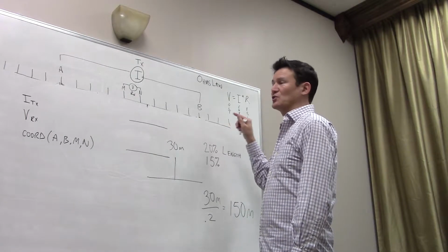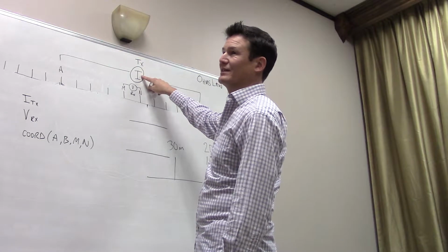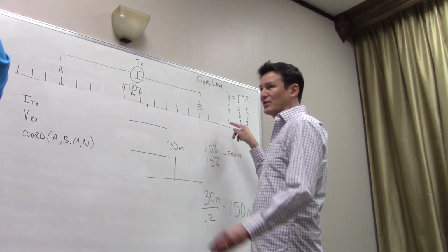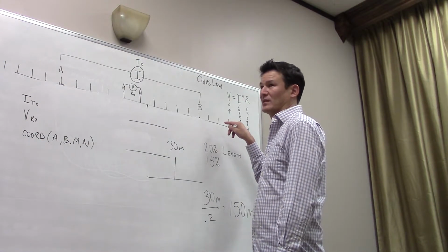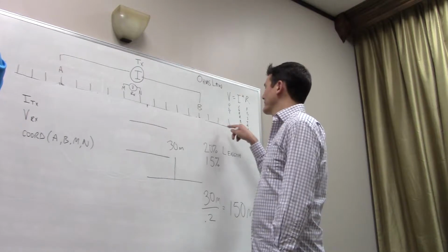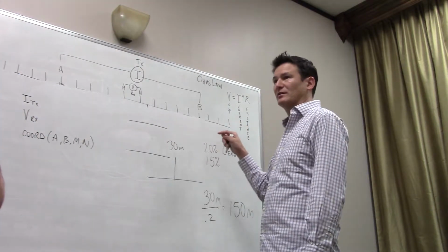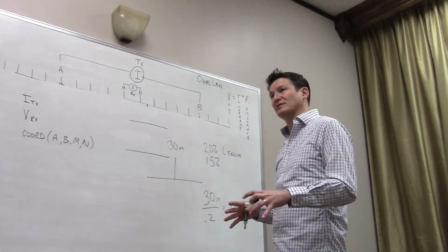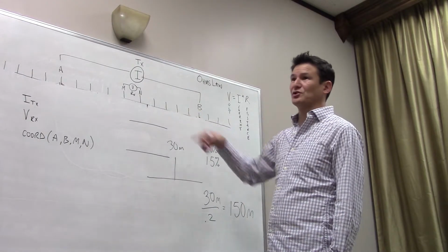Meaning how? Because what's important for us, our transmitter, our signal, is the current. So we have to get enough current in there. And if the ground is very dry, in your case it's dry sand, that's probably a more difficult case. Pouring water on the transmitter stake, that area, right? Usually we pour about a pint of water, or a liter or so, at the stake to increase the surface area of that stake. Okay. And that will increase the amount of current you can put in the ground.